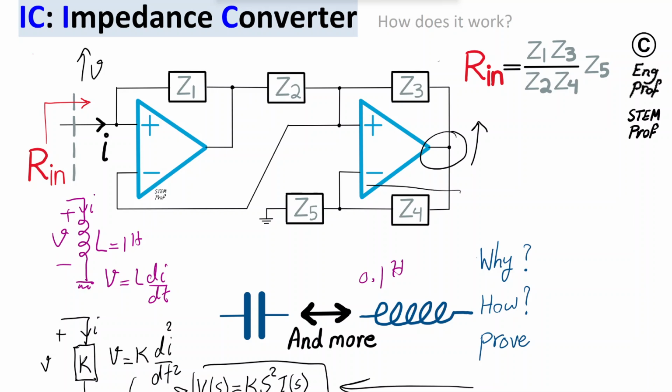As a result, there is a voltage divider across Z4, Z5. If this node is increasing, the mid node is also increasing, and that means the negative terminal starts increasing as well. So the moment the positive terminal jumps or increases, the circuit is wired in a way that the negative terminal also starts increasing. That is the indication that we have proper wiring in the circuit and connection to the terminals of the op-amps.